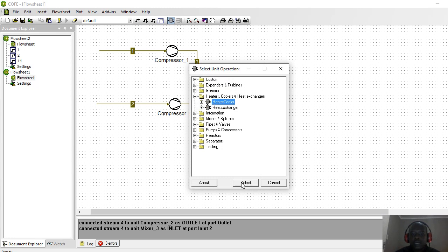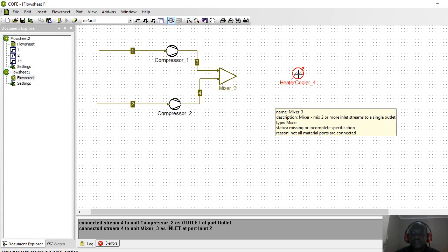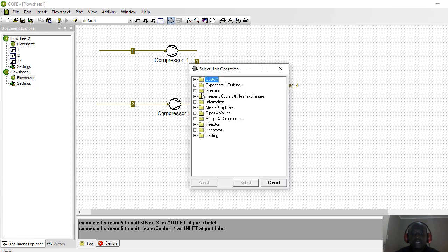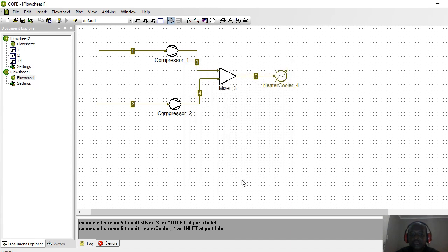By the way, I'm just going to do a simple setup here, but usually for reactions where you're working at high temperatures, you want to use up the heat that is left over in the product stream. So you do a product feed heat exchange system, which will allow you to do that.